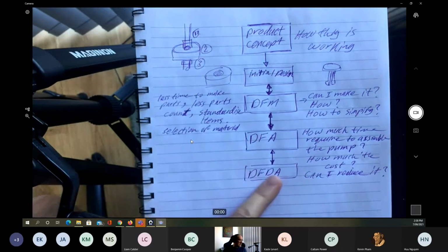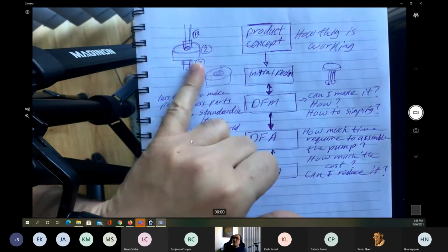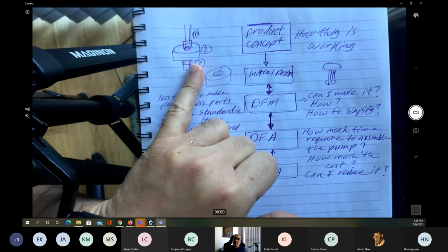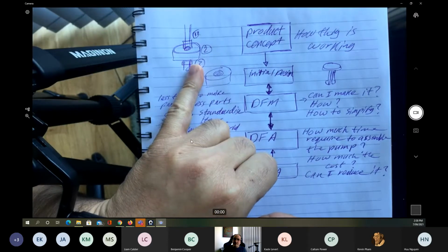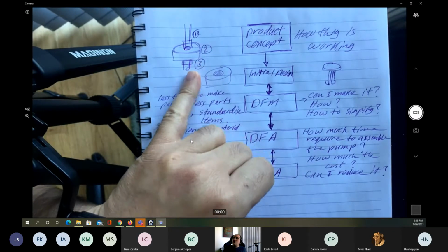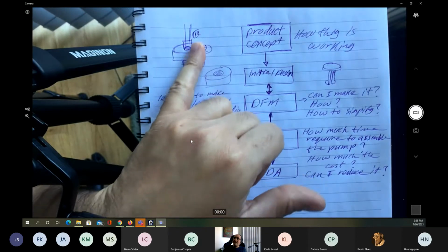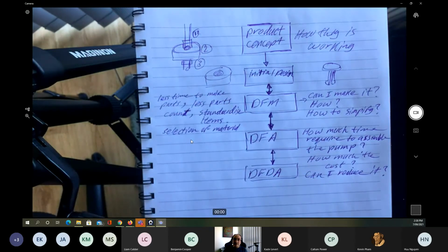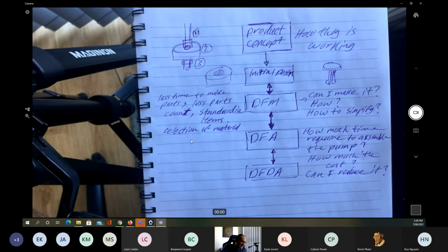So you can talk about that in design for the assembly, using plastic nuts instead of the metal nuts, or try to coat the shaft with a material that is going to prevent the rusting. This will make the time required to assemble the pump the same as the time required to deassemble the pump, and this will make the assembly process easier.